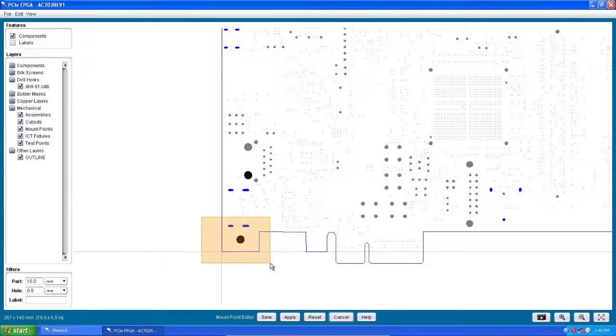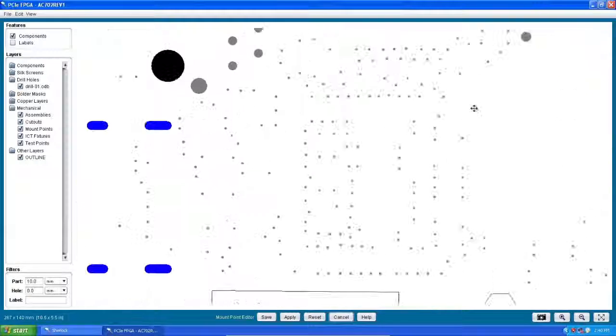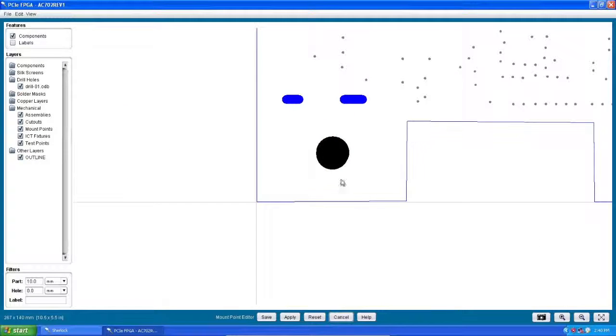And you can barely tell they're there. But if you zoom in, you'll see them. You have to be careful. You can just barely see that there are two there. If you do that, it'll cause a meshing error. So never put one mount point on top of the other. One mount point's enough. You don't need two in the same place. It doesn't make sense from a physical perspective anyway.